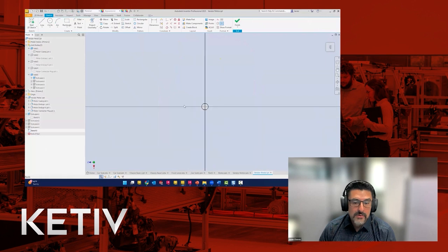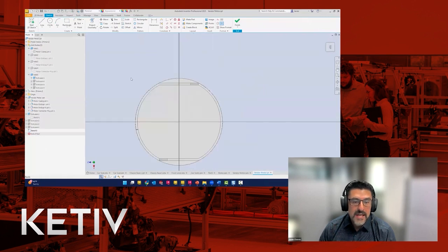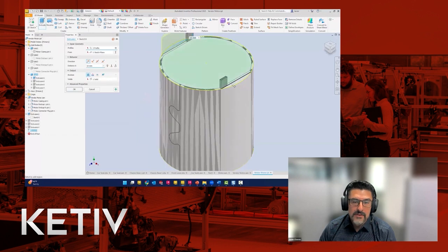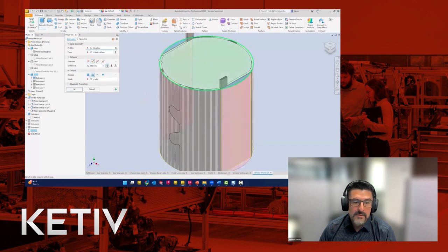And what we're going to do is we're just going to sketch on top of the solid and use just regular CAD modeling tools to cut away the information. And we can project the geometry from the casing so that we know where that cut is exactly, and continue to use just common sketching tools. So now we're really combining the 3D model with some modeling. But again, it should be less work in terms of measuring that, so that again, we can use common extrusions and cuts to get to what we want.